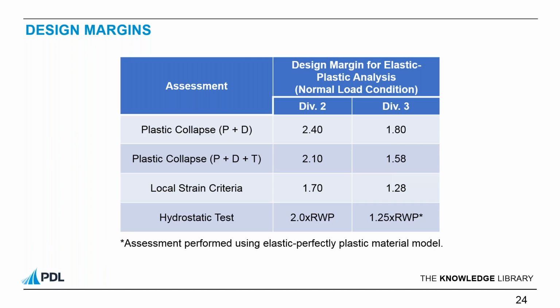So the first part of that is saying, if you've got an existing structure which is comparable, and it's survived for a long period of time, then we can infer a level of confidence in terms of fatigue performance from that. If you're just moving into a new market, a higher pressure market, you're not going to have the luxury of that. And there are two methods, method A and method B, which basically allow you to figure out whether or not it's fatigue sensitive. They're both step-by-step processes.